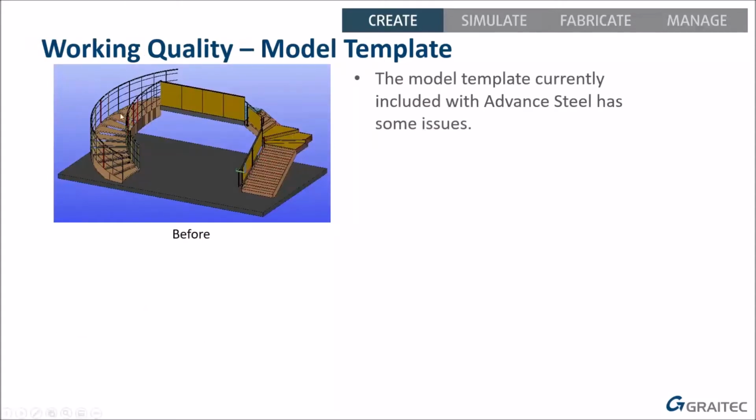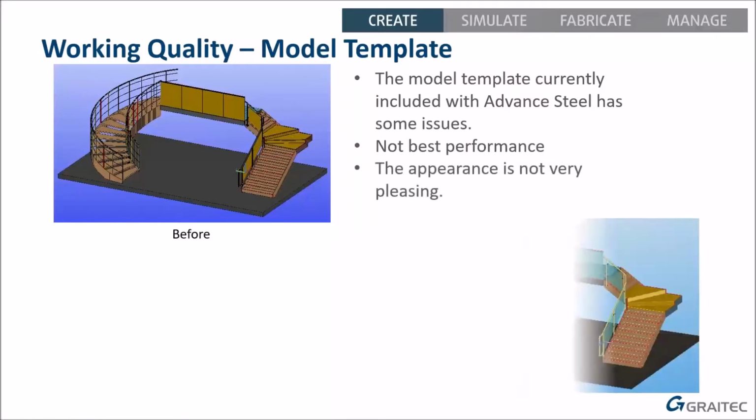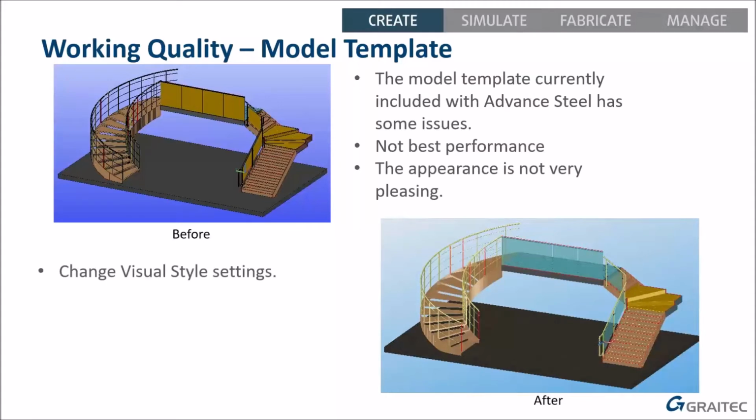So there's the horrible template provided with Advanced Steel. It's not brilliant. It doesn't give the best performance because it's not using the up-to-date rules for the visual styles, and it's not very nice to look at. But do some changes to the visual style settings, and you'll improve the performance.